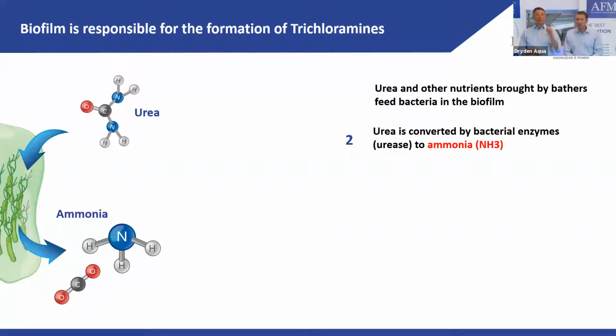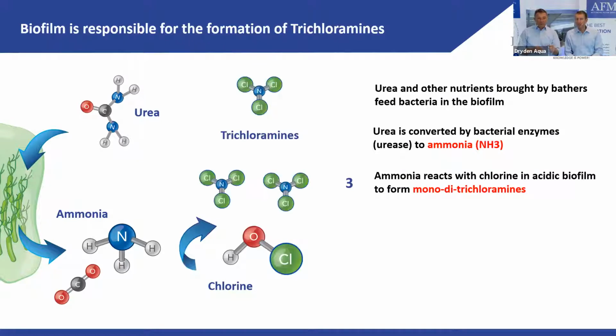I do it black and white, reality is a lot more gray. If you have sand, you end up with 0 urea and 90% of ammonia. If you have a bioresistant filter media like AFM, you stay with 80% urea, 10% of ammonia.